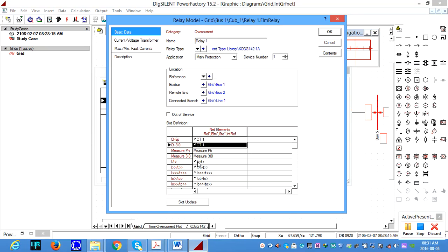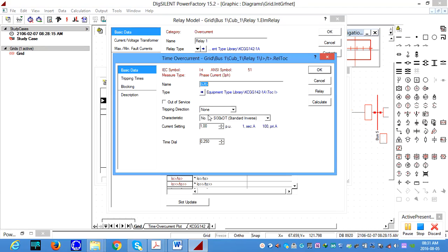And we also want to make sure stage 1 and stage 2 for relay 1. For stage 1, if you look, the stage 1 must be standard inverse. You select from the standard inverse. In the first exercise also we used the standard inverse, but you used IEC, but that comes with the specific relay model 751, but this is Alstom relay model, so there is no IEC. They are saying DT, standard inverse. Okay, definite time standard inverse characteristic curve.